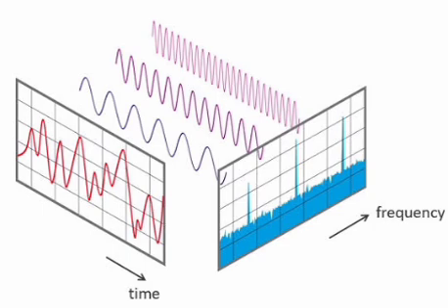If x[n] has DFT X[k], then linearity: a x1[n] + b x2[n] ↔ a X1[k] + b X2[k]. Time shifting: x[n − n₀] ↔ e^(−j2πkn₀/N) X[k]. Shift in the k domain: x[n] e^(j2πk₀n/N) ↔ X[k − k₀]. Conjugate symmetry: x conjugate of n.